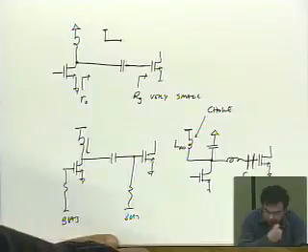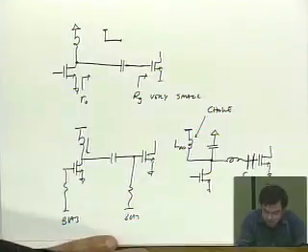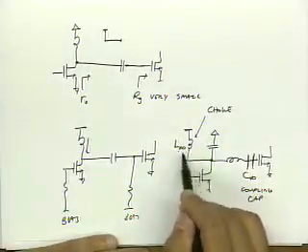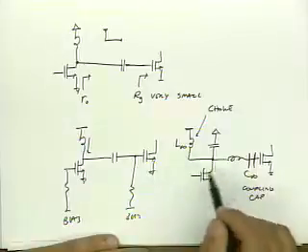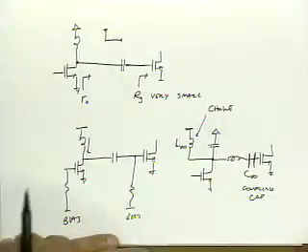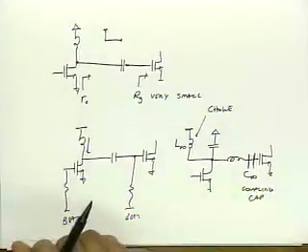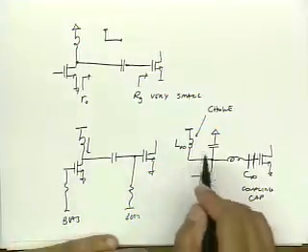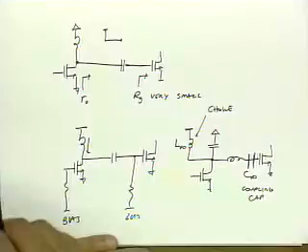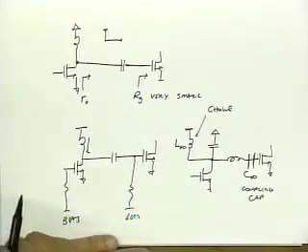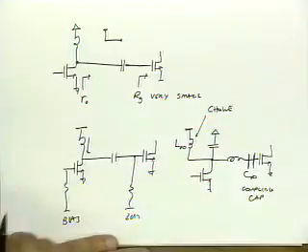It's a good question. You can build them on chip. In fact, in practice, you would never really make this very large. Much better to make this part of the tuning network that's already here. But there are certain cases where you absolutely do need a very large inductor, say to drive the tuning line of an oscillator. You can build them on chip as large as hundreds of nanohenries. So for gigahertz frequencies, that's effectively a choke. But if you're talking about megahertz frequencies, certainly it has to be off chip. You can't make them on chip.